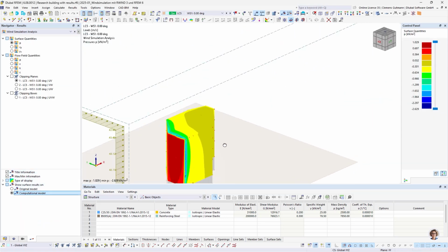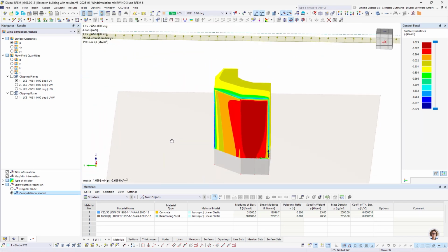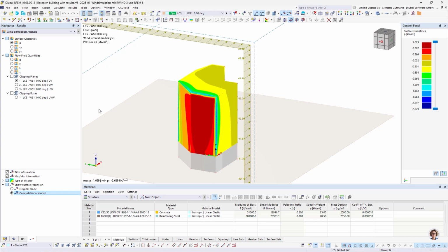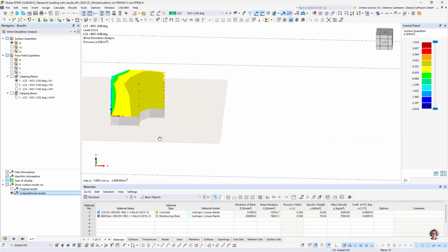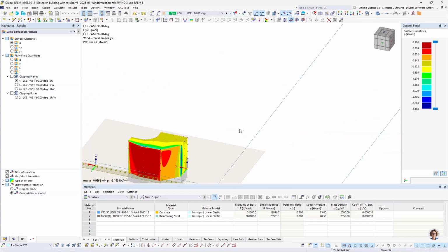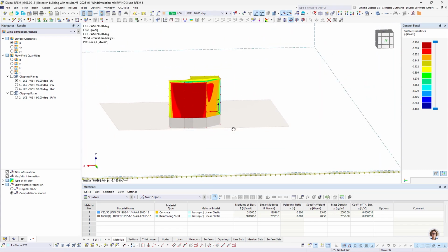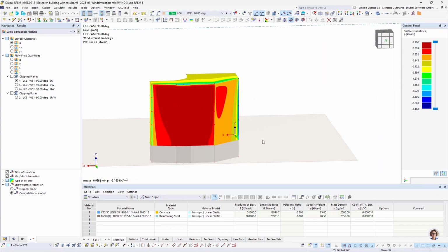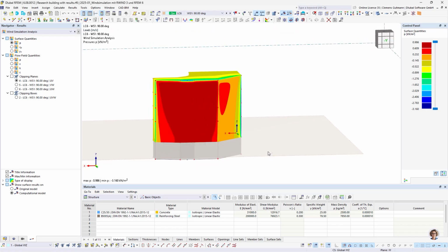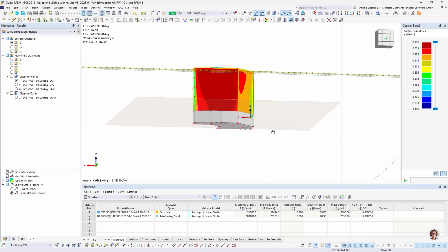And we can here now inspect the pressure, the wind pressures, and also the pressure coefficients, as well as the flow field quantities, whatever we want to know in the different directions that we analyzed, and now can get a better idea of how the building reacts to wind exposure. And as you can see, the terrain that we set in the beginning is now displayed,